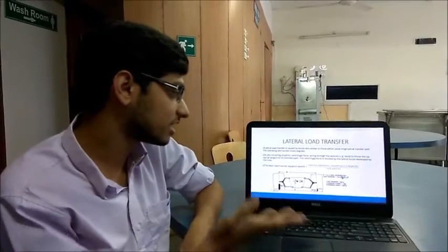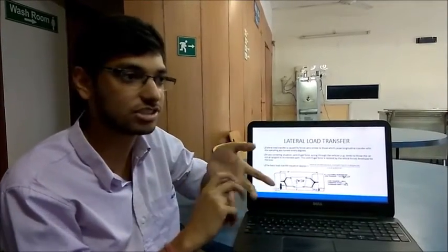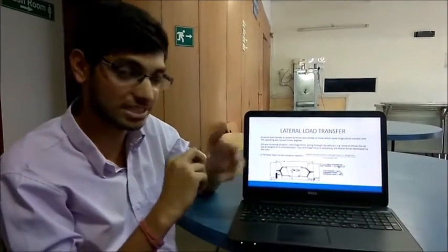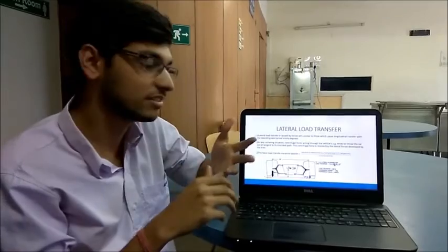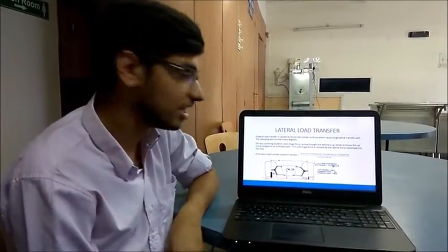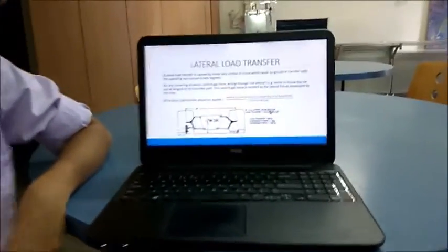So tangential to its intended path. This centrifugal force is resisted by the lateral forces developed by the tires, which is the cornering force. That depends on the vehicle geometry and the loading on the tires. So the basic load transfer equation applies again, as it applies in longitudinal weight transfer.